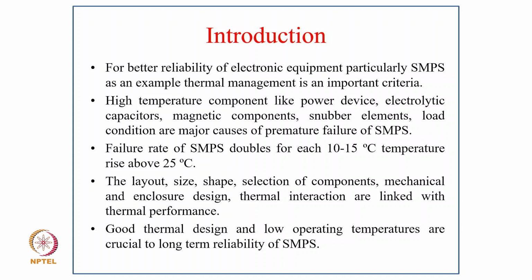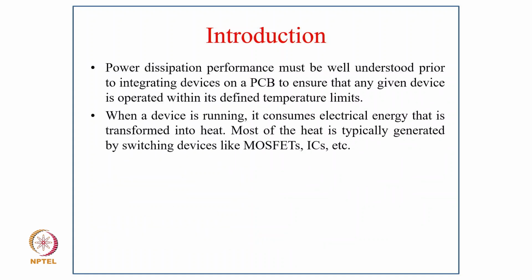So the layout, size, shape, and selection of components, mechanical and enclosure design, and thermal interaction are linked with the thermal performance. Good thermal design and low operating temperatures are crucial for long-term reliability of switch mode power supply. The power dissipation performance must be well understood prior to integrating the devices on a printed circuit board, to ensure that any given device is operated within its defined temperature limit.